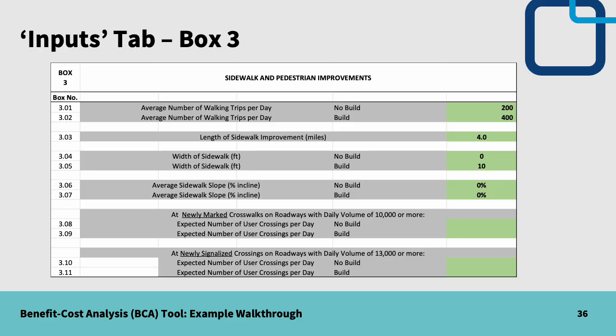There are 2 more inputs here related to marked or signalized crosswalks on roadways with a certain daily volume threshold. While we are going to install the RRFB, we already analyzed that separately, so we will just keep these at 0.